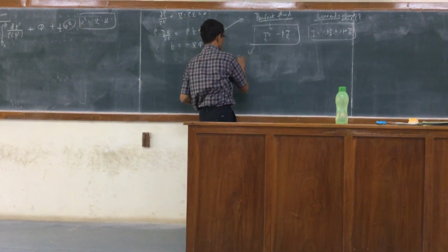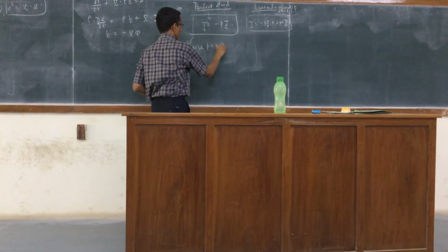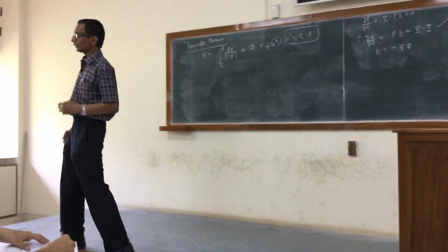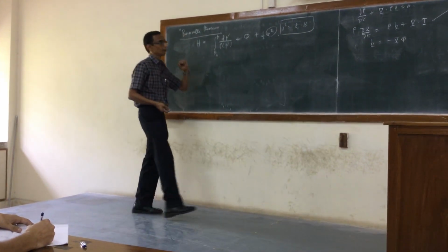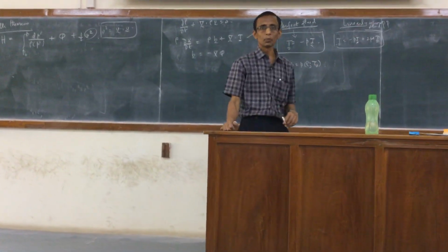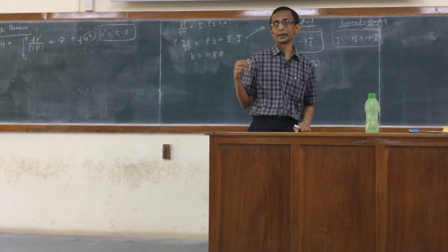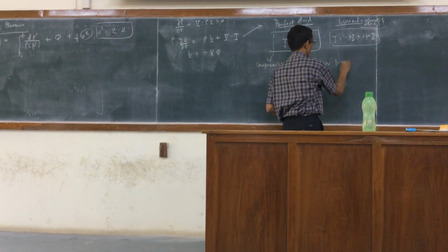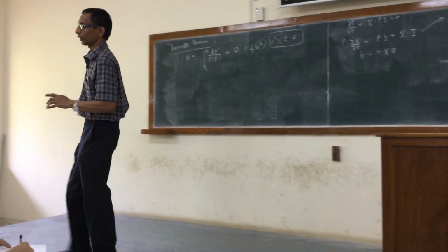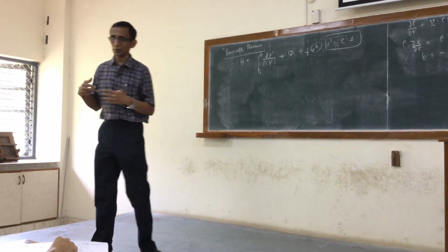But if it is compressible, then I pointed out that P is equal to P of rho, T. Now, in the case of the Bernoulli theorem, we generally assume that the temperature is fixed at some value, so that the pressure is dependent only on the density, or the dependence on temperature is not that much. We can simply neglect it, so that the pressure becomes expressed as a function of rho. All these conditions are built into the Bernoulli theorems.